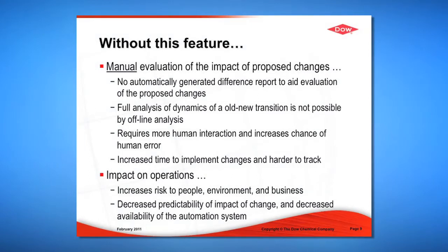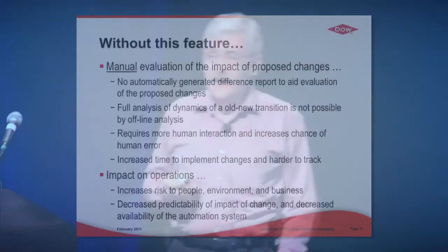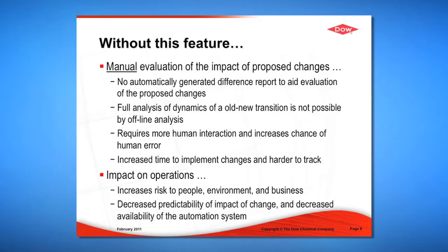The bottom line in terms of operations is that not having this feature increases risk, because now you're making changes which you may not understand the full implications of. I talked about the load, evaluate, go, or the hot loading. The converse, without that capability, is basically load and go, or shotgun loading, if you will. Pull the trigger and hope for the best. And that definitely can increase risk, and you have less capability of predicting the impact of changes.